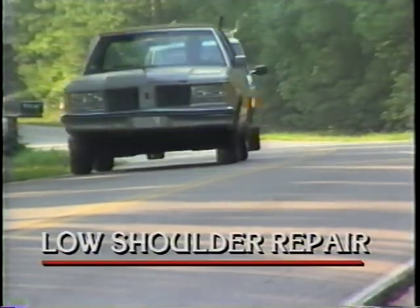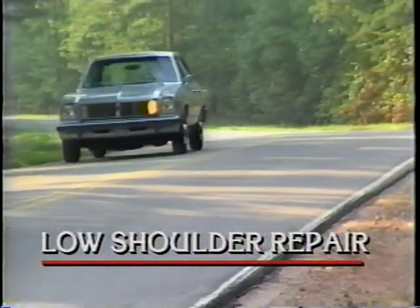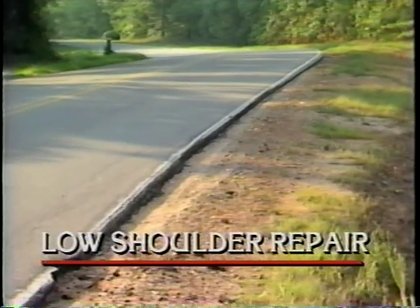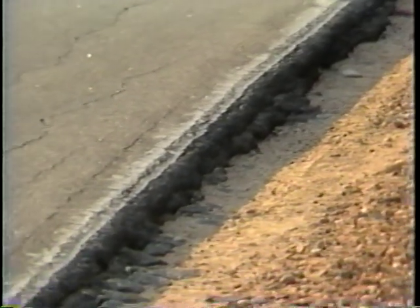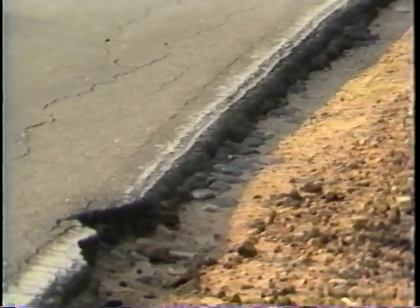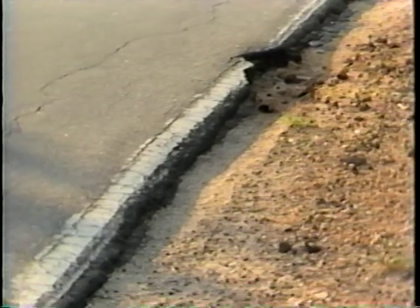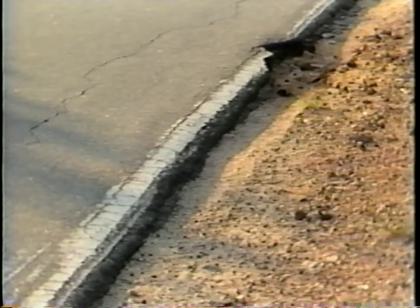Now, let's look at low shoulder repair. A low shoulder condition is generally caused by erosion or traffic riding on the shoulder of the road. On a narrow road, the outer wheels of a vehicle may ride at the edge of the pavement or possibly off the edge. This is especially true where there is a lot of truck traffic.